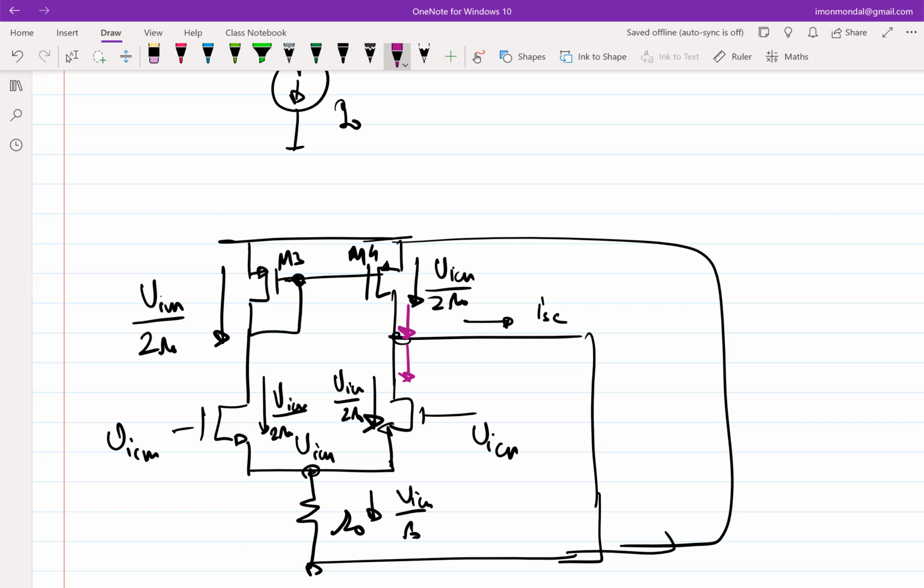It was not 0 in the earlier configuration, remember? Because when the resistive load was there, there was no current mirroring effect. So only the bottom part of the current was flowing into the short, developing a voltage in the Norton equivalent. But in this case, the top part of the current cancels out the bottom part in the common mode sense. In the differential sense, they were adding up; in the common mode sense, they are cancelling. Okay, so you are getting 0.